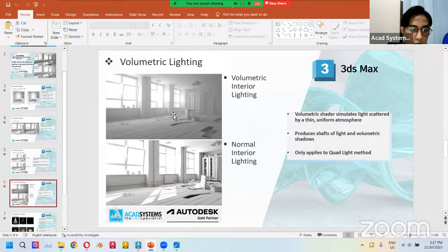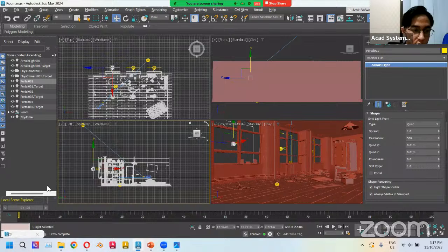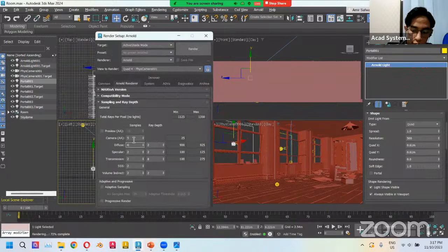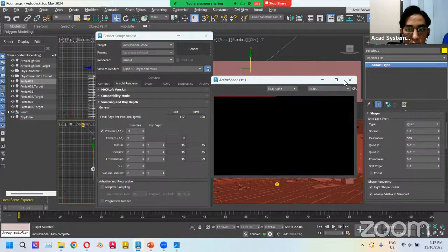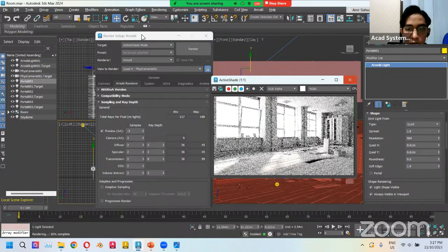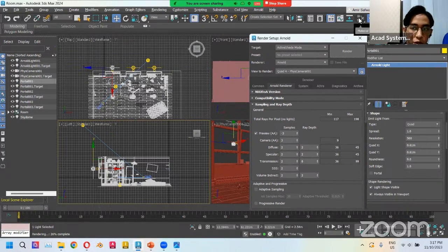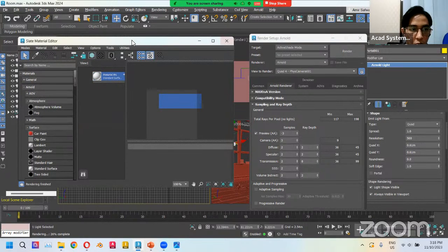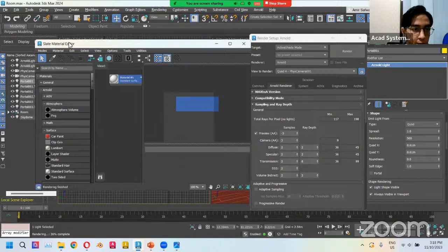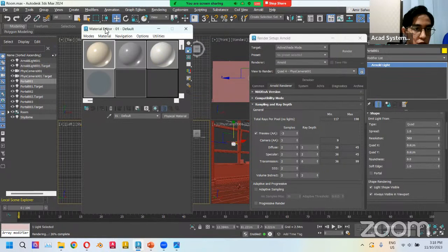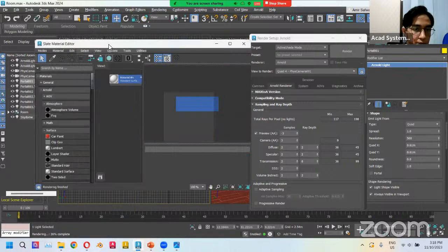So to make these settings, we are going back to 3ds Max and reverting the settings, turning on preview, and then I'm going to go ahead on the top over here. We need to turn on the material editor. Over here you should have select material editor. If you don't see this tab, click on mode, and then you should see select material editor.